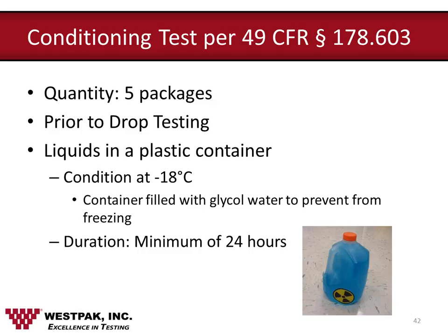if you test the liquids that Jorge was talking about earlier in a plastic container, you condition them to minus 18 degrees C. The reason why you condition these packages, these bottles, to minus 18 degrees C is because we want to test what happens when these bottles and closures get brittle and you drop them.